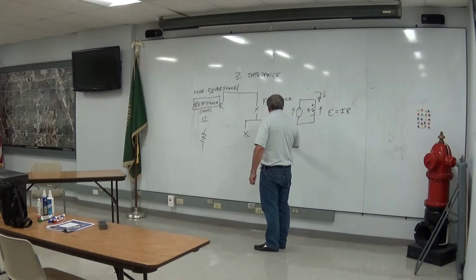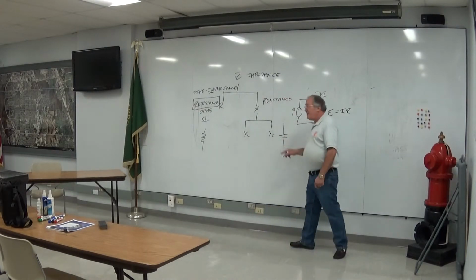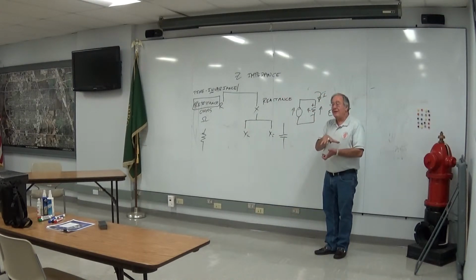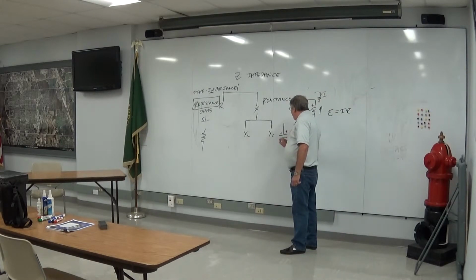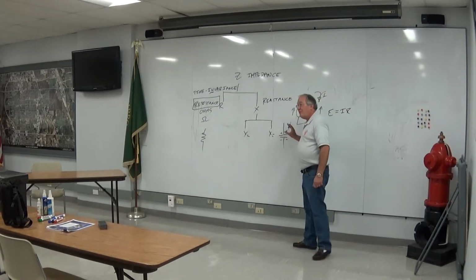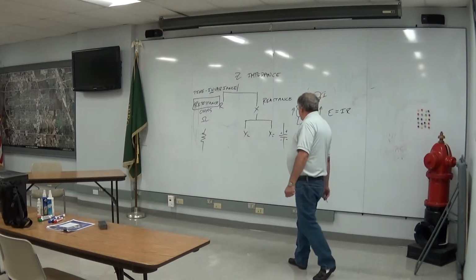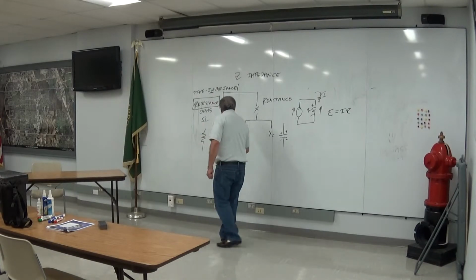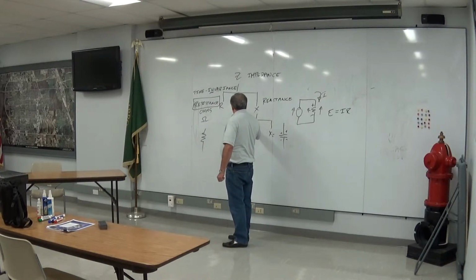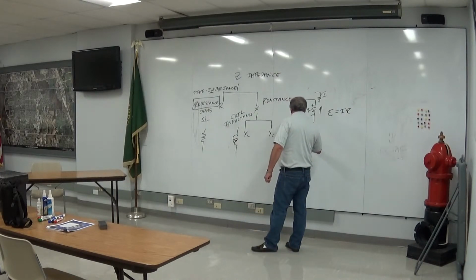The C is for the capacitor, symbolized with these two parallel lines, which really is a good graphic because it shows you pretty much what a capacitor looks like functionally. It'll accumulate charges on one plate that are opposite the charges of the other plate, and it will store energy doing that. And this is X sub L. Greg used the word coil. Well, I use the more broad term, inductor, or inductance, just like the word over here is capacitance.